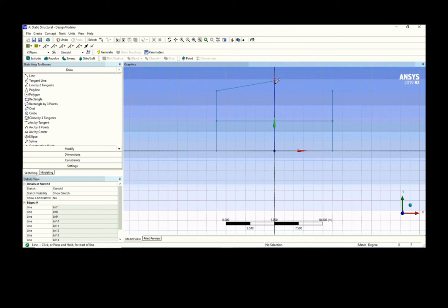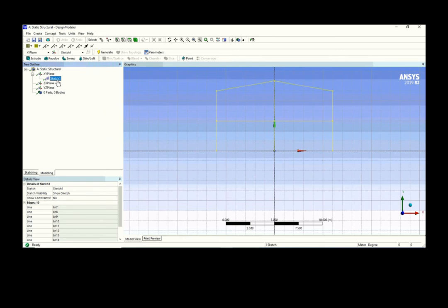We try the plane first. The whole idea is you get this body out first. That gives us, I think, a similar model to the one given in the problem. What you can do now is click on the sketch, then go to Concepts. This is just a sketch, so you have to create this line from the sketch itself.